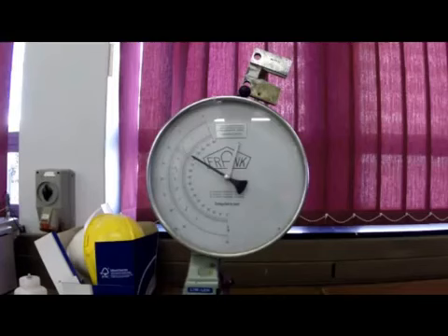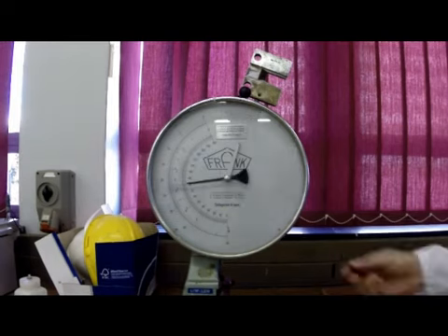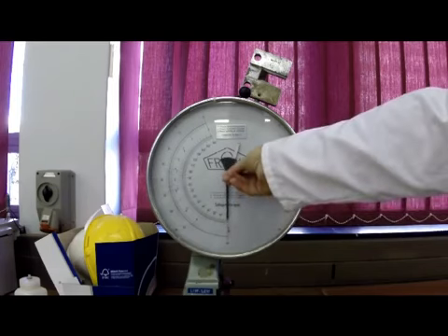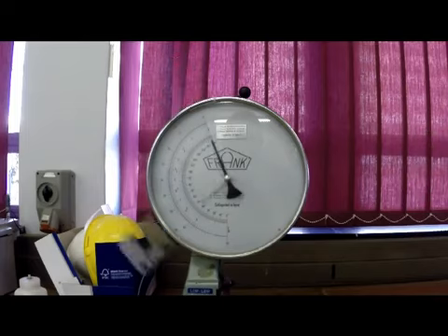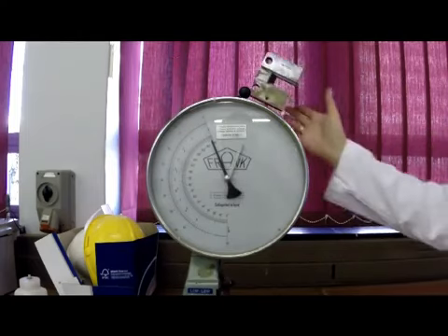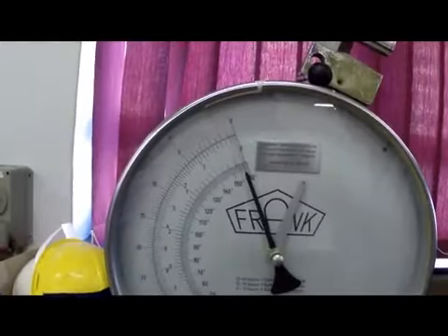The Charpy impact tester makes use of a hammer to impact the sample and determine how much energy the sample absorbs in the process. In order to accurately determine energy absorbed, it is necessary to determine the energy lost in the system due to friction. This is achieved by performing the impact test without a sample in it. First, turn the needle to the 0 position. Then, press the lever to release the hammer and allow the hammer to perform at least one complete swing. This will generate a reading that corresponds to the energy lost in the system due to friction.